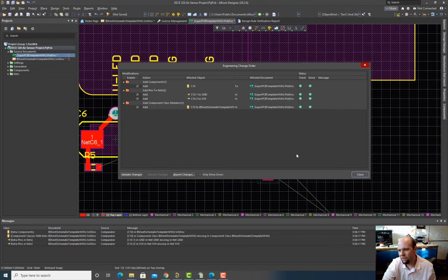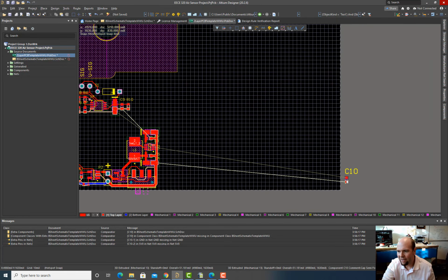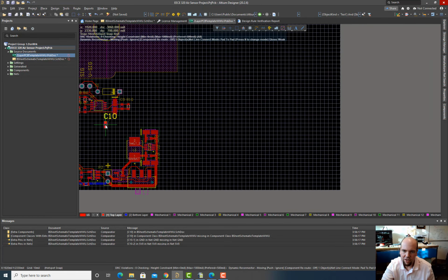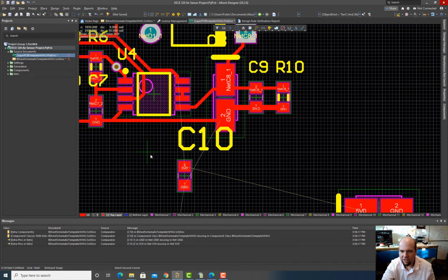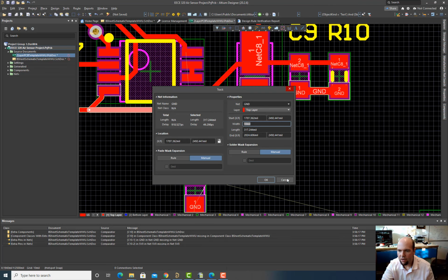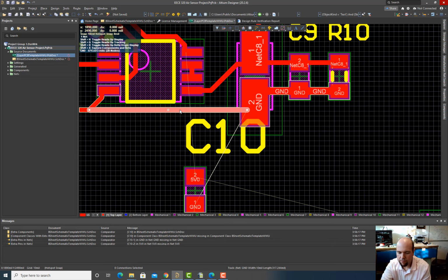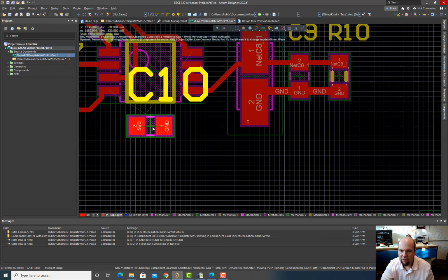So we're going to give ourselves a capacitor just to smooth out the power. For stability, a lot of times, it's not going to be a case for us because it's kind of a low-speed circuit, but with op-amps, it's just good to have a capacitor near the op-amp itself between the rails. Didn't like that. So I'm just going to put this here.